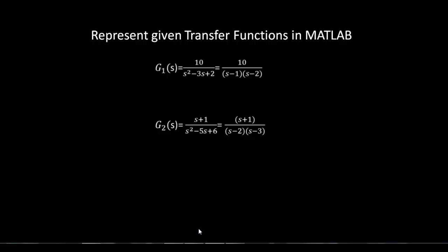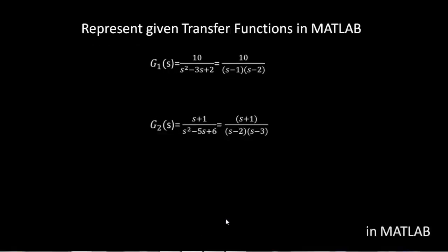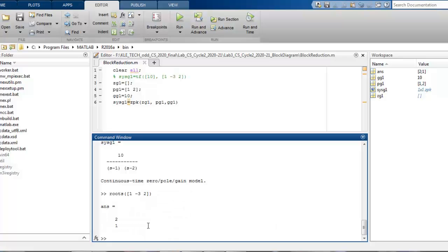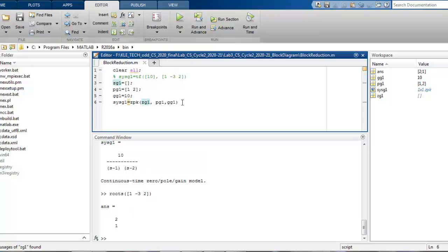Remember, when I want to do this in MATLAB, I need to know what the numerator coefficients and denominator coefficients are for the algebraic method, where I am using the TF function. So numerator and denominator, numerator is 1, 1. Okay, first let me write that in the, okay, let me comment this.